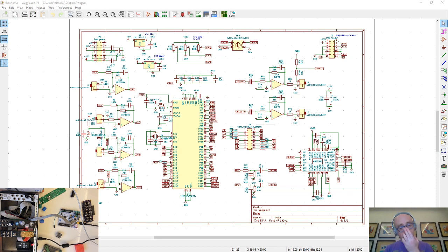I could probably use the peripheral, although I haven't tried, and I've not enjoyed using the peripheral on the STM of I2C. So I decided that this time I would just bit bang it by hand, because we only use the I2C bus to configure the thing on boot, and then we ignore it after that. So it's not very painful to do it slowly. Okay, I will double check the chat, and then we're going to go into coding. Everyone seems happy. So like I said last time, probably this is going to go horribly wrong and I won't get anything done that I wanted to get done, but we'll see how we do.